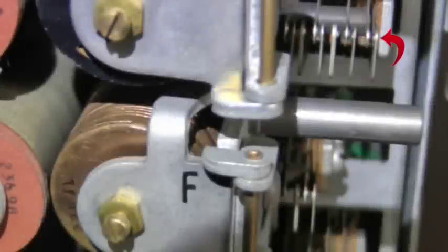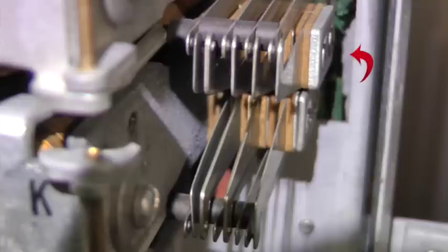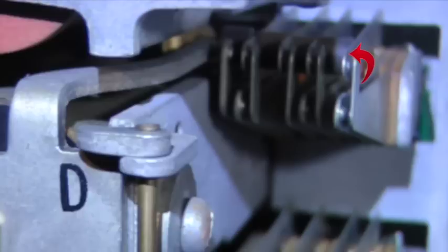B released also releases F, K, and D. The release of the K relay removes ground from the sleeve wiper. This removes the busy indicator for the called station from the sleeve terminal of the connector banks and releases the station's CO relay in its line circuit. At this point, the energizing path for the release magnet is closed and its armature operates.